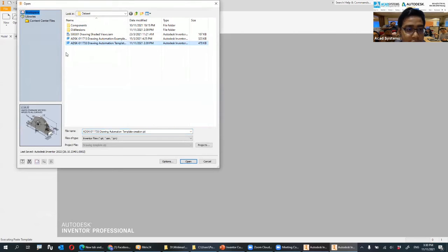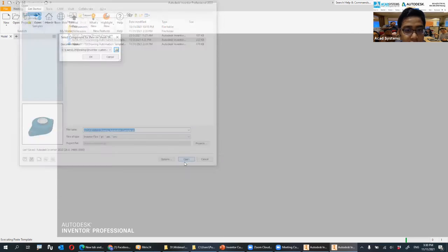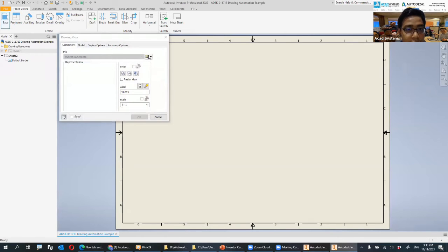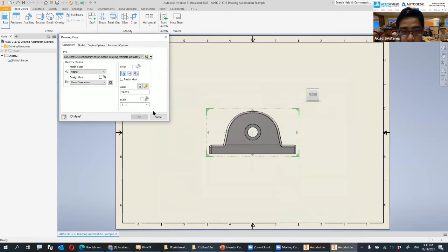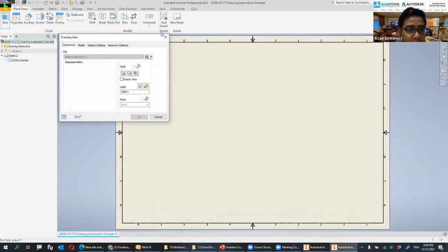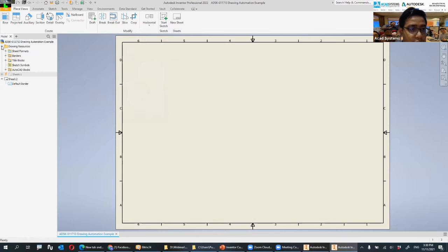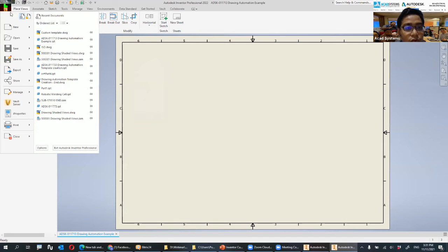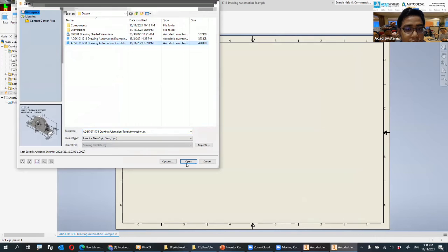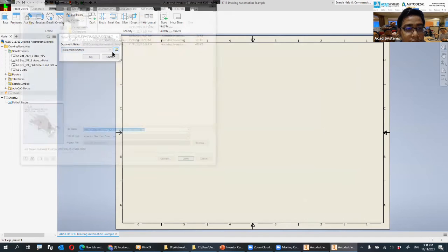If I choose other types of drawings, for example, I believe this one, so if I open this one, so let me enter back this one. Right. So instead of open from base, what I can do is go to my drawing format over here, go to my sheet format and find my A3 view over here. Either you do from here or you can also do it from the new and select from here as well. So I select this one, open.